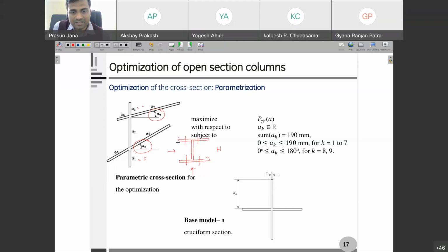And in an H section generally, your web is smaller and the flange is larger. Okay. And in an I section, the web is larger and the flange length will be smaller. And there you can get T sections also from here, like for certain parameters, if you set, you can get T sections like this. You can get also C sections from here. So this is actually a typical parameterization which can give many regular sections, and as well as the irregular sections also you can get.